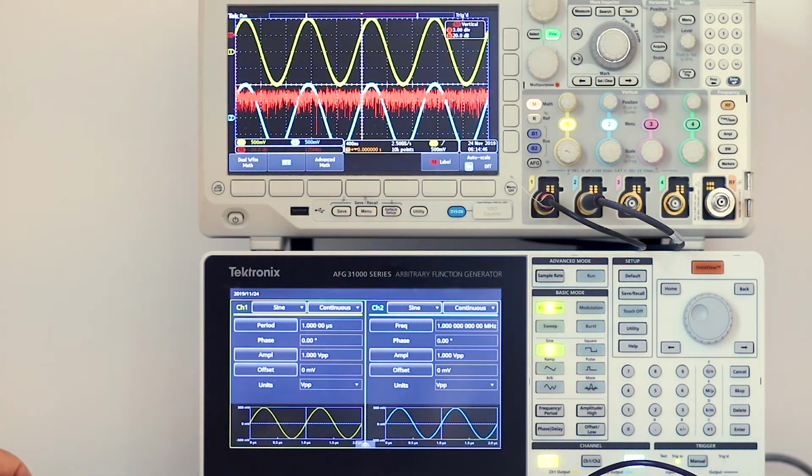Doing the fast Fourier transform, only one source is required. Using multipurpose knob A, you can make two the source, but the frequency domain representation looks the same, since the waves displayed in the time domain are the same in both channels.